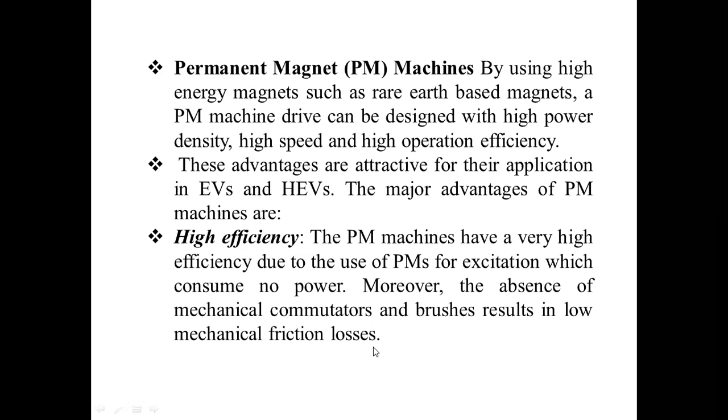Okay, mechanical commutators and also the brushes. We are eliminating these two main parts of the normal conventional DC motor, compared to the permanent magnet DC motors. Here the frictional losses are reduced. Therefore, there is no noise, and the shaft output power should be an increased value.